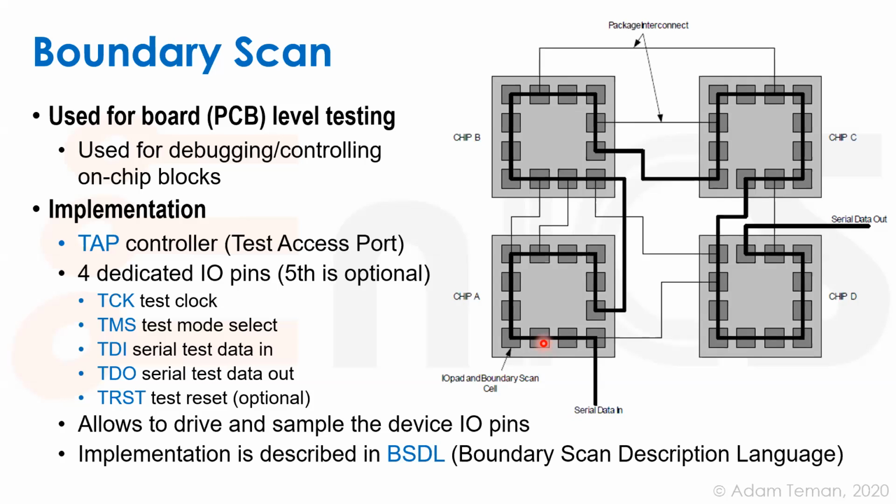They wrote a language called BSDL, Boundary Scan Description Language, to define the tests that actually do this. But in the end, it helps me test my board in an electrical way without using that bed of nails. So basically, every chip you make, you have to implement this boundary scan on it.